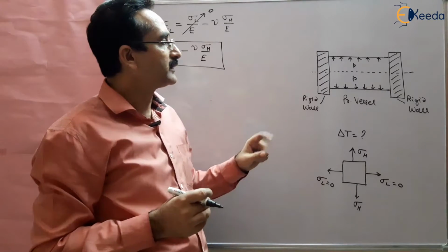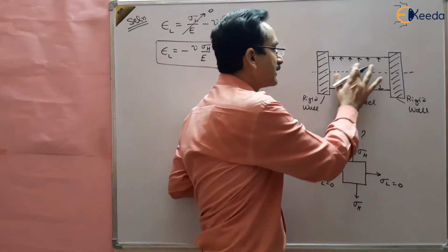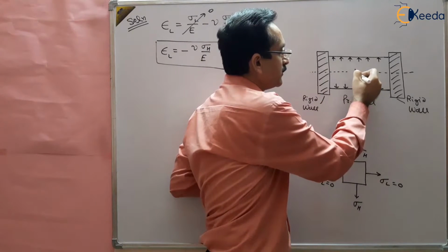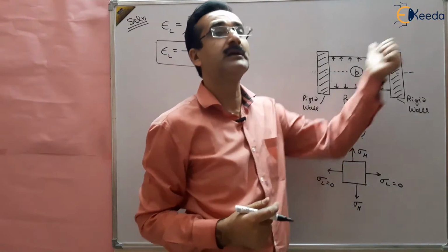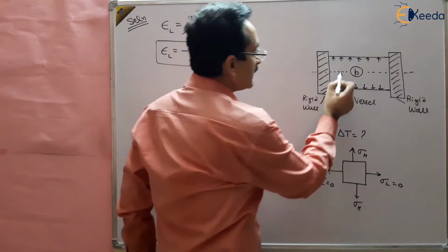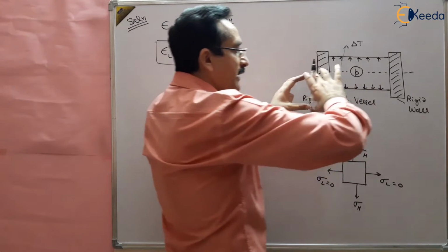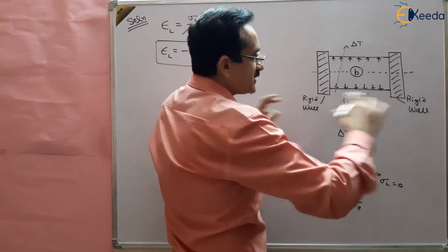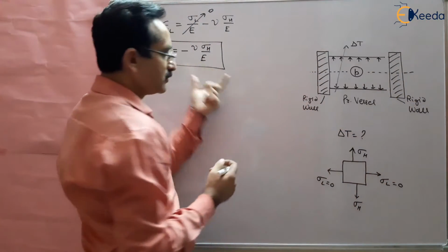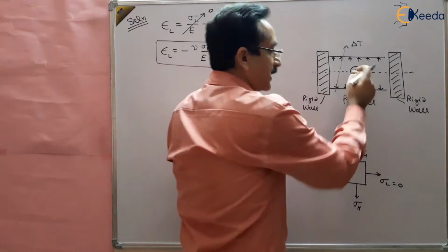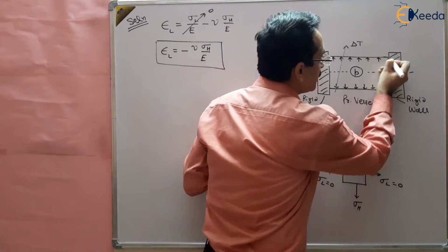Now, we want that the gas which is producing this pressure should not leak from this pressure vessel. So for that, the temperature of this pressure vessel is increased, right? And when there is an increase in temperature, say delta T, what is happening? There is expansion in the pressure vessel, and the expansion is such that the gap which was obtained due to the hoop stress, due to the applied pressure, is now filled due to the temperature rise.